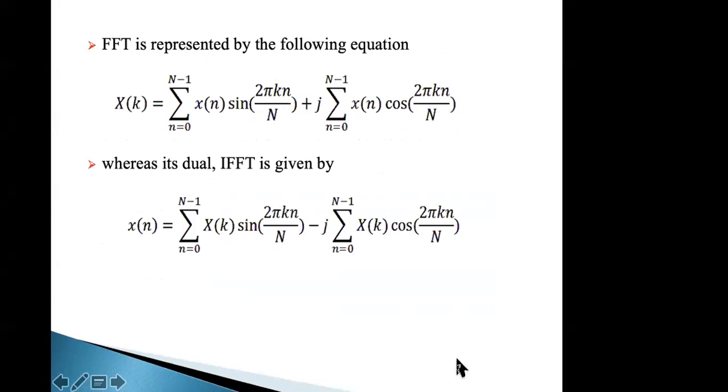If you use an FFT in the frequency domain, my signals are multiplied by sine and cos, right? So this is the representation following the FFT equation. Similarly, in the IFFT equation, I'm using a frequency domain signal and they are multiplied by sine and cos. The resultant will give you a time domain signal. So in my transmitter and receiver, I can use these principles.